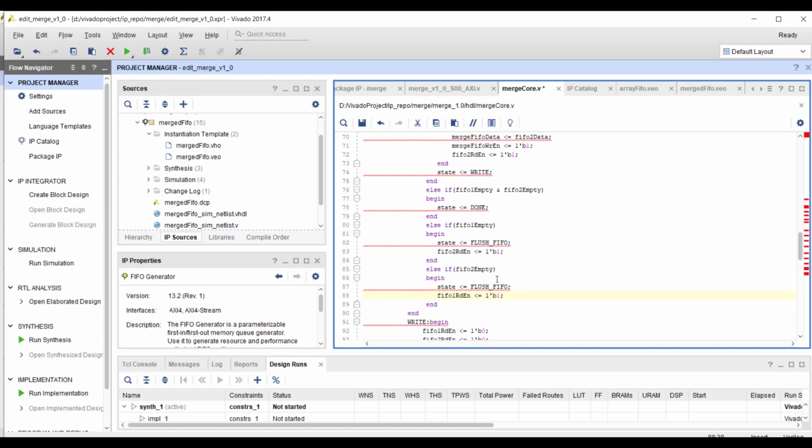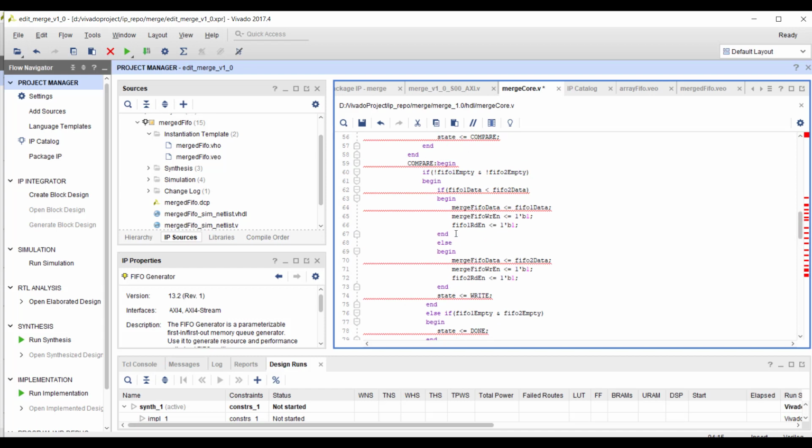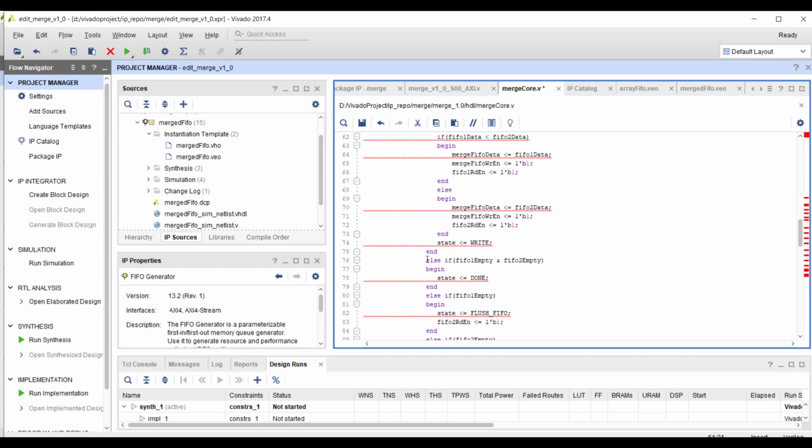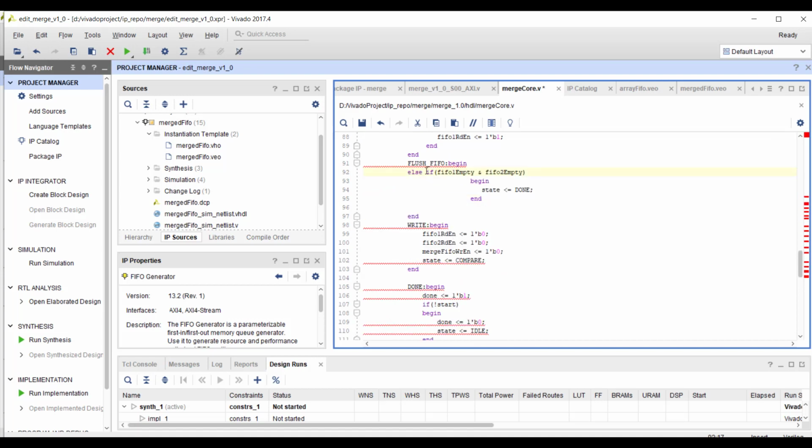Okay, so you made this signal high, and he will see the signal only in the next clock. But this 54 has already prefetched some data, and it is actually available at the output at this point of time. So in the flush 54 state, again what you will do is similar cases. If both 541 and 542 are empty, you can go to the done state.